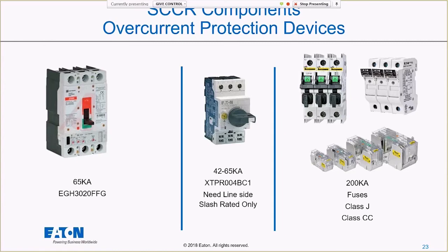65 kA breakers cost more than 10 kA breakers. But you could certainly have breakers in that if there is a reason, if it has a really good rating with whatever is downstream. You can use something like a manual motor protector. Rockwell has a ton of these, right? So use this manual motor protector. It has some really good combination ratings with downstream devices. You use this, you're probably going to get between 42 and 65 kA. You're using a combination motor controller rating.